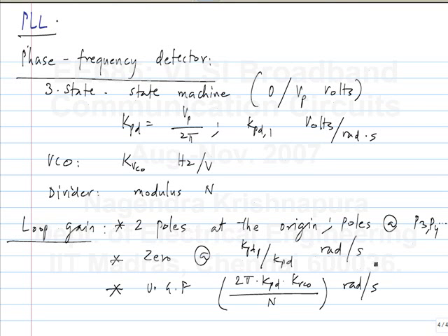And it also depends a little bit on availability of other components. Maybe in some cases, some reference frequencies are available more conveniently because crystal oscillator modules are available for those frequencies. So based on that, you may have to vary n. Okay. And finally, the same system may have to work at different data rates.